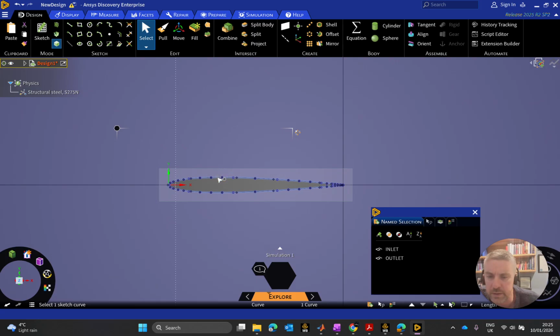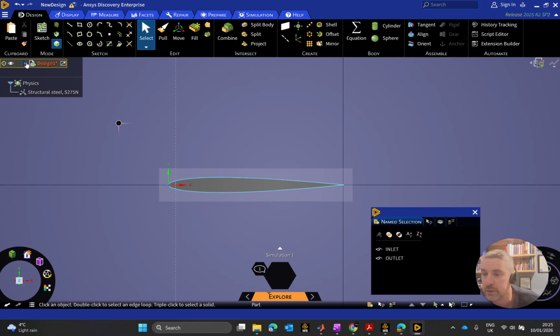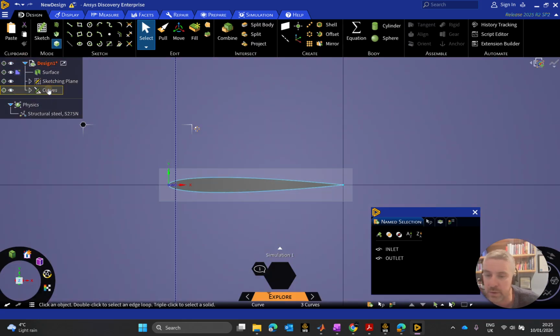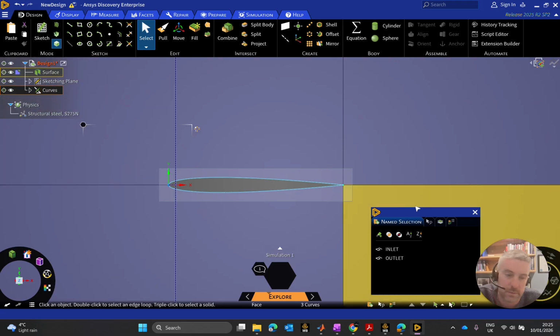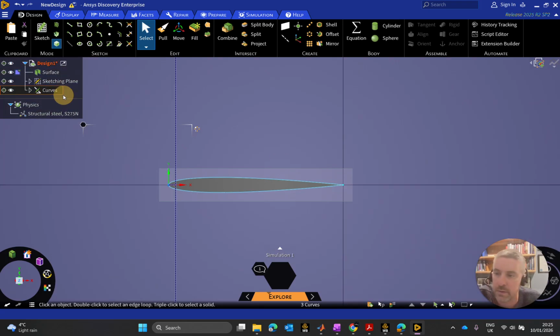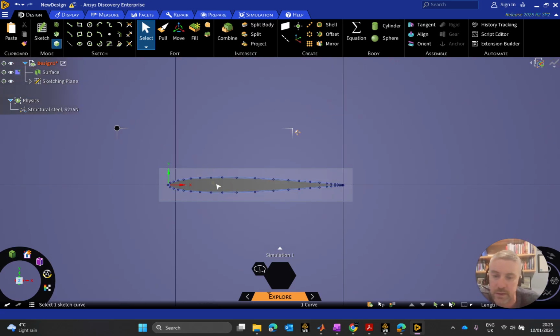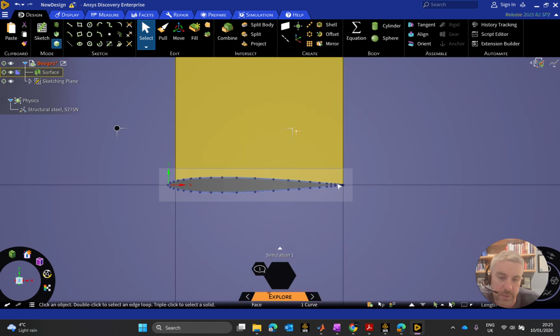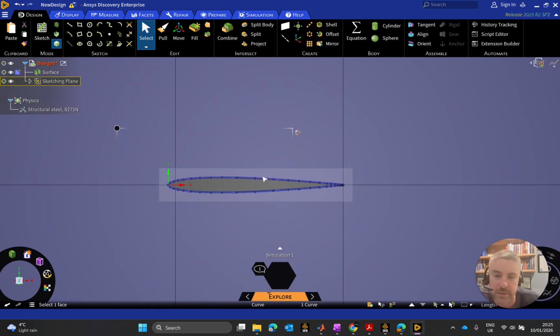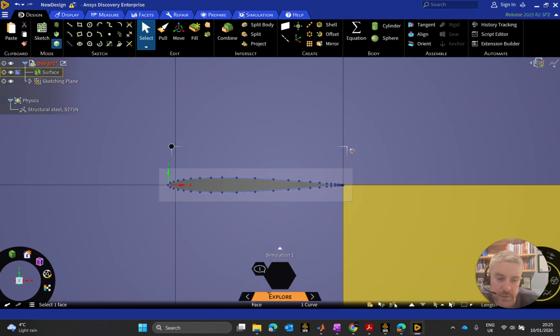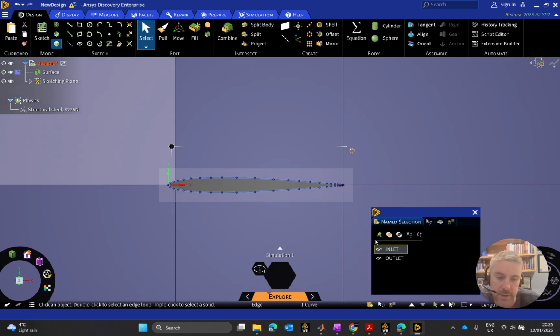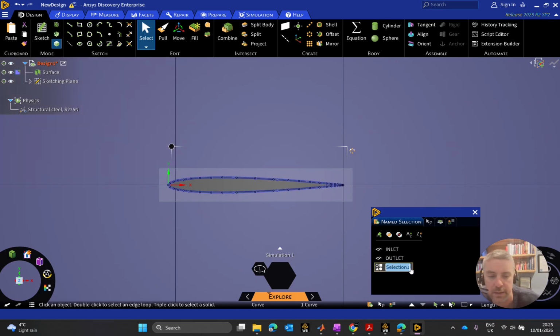But what I will indeed do, before I do anything else, is drop down my design up here. See this, curves. Actually, let me just take this name selections away. Curves. I'm going to delete that curves, because now when I've deleted the curves, I can get access back onto this boundary of these split regions. So I'm going to select that boundary, come back then into my name selections, add a new name selection to that, and then call that wall. No, it's not a wall, it's a surface, it's an airfoil.